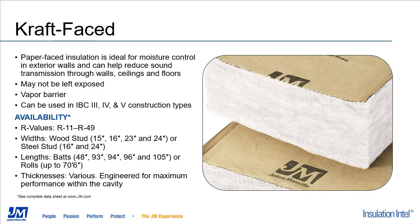So unfaced and kraft-faced batts are the most widely used products in the industry. Kraft facing is also known as paper facing and is an ideal economical vapor barrier facing. But because it is paper, it is combustible, so it cannot be left exposed, and it doesn't have an ASTM E84 surface burning rating. And it can only be used in IBC 3, 4, and 5 commercial construction types. And the availability of this product is going to be very similar to unfaced batts.